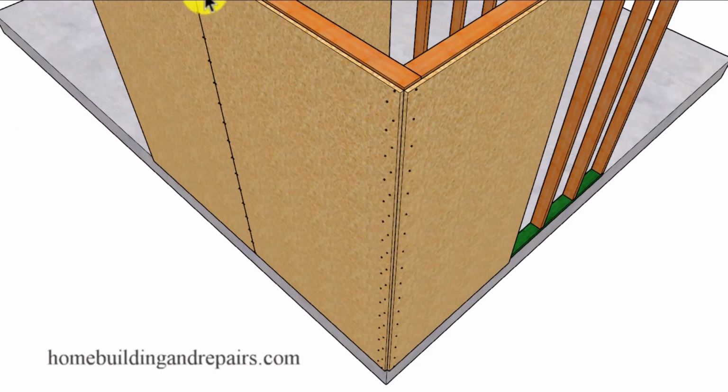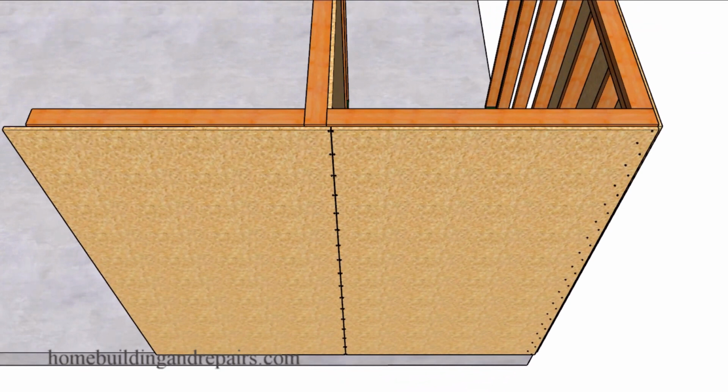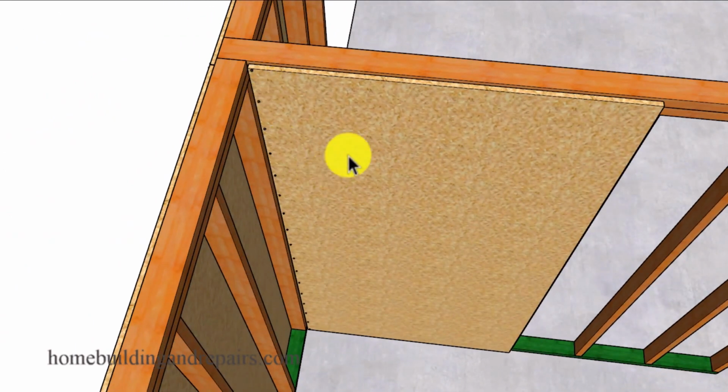And now for the reason why I made the video, I've seen this happen too many times, where the structural engineer might require a hold down over here and intersecting walls with shear panel. It's something I recently came across that inspired me to make the video. And that would look something like this, where we have our shear panel on the interior wall, starting over at this point here. However, it's not starting at this point over here.